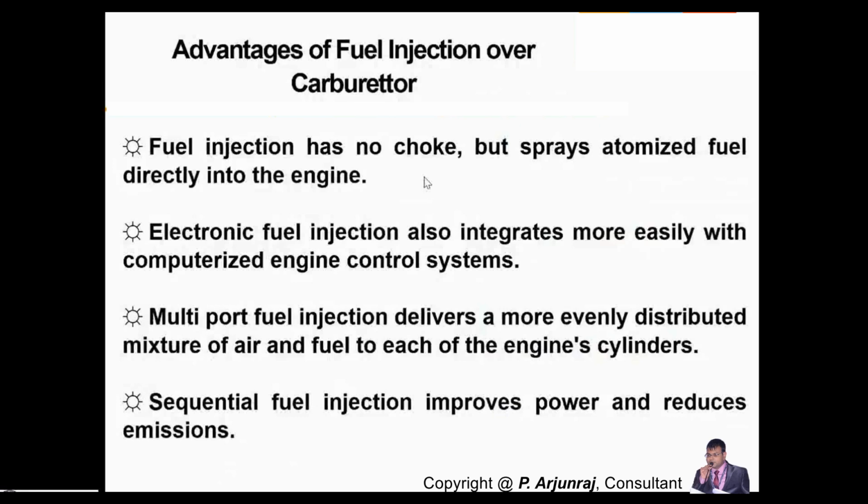And again, EFI, shortly called electronic fuel injection. It also integrates more easily with the ECU, the engine control system, whereas this is not there in the case of a carburetor. Again, you have a multi-port fuel injection, which will deliver a more evenly distributed mixture of air and fuel to each of the engine cylinders. So I told you, you can get a distributed amount of air and fuel equally, whereas this is not possible in the case of a carburetor.